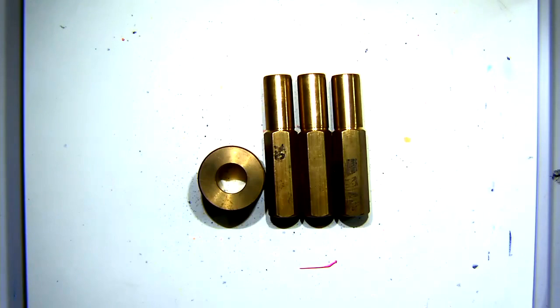And that hole is, as I played around with last time, I could put verniers and calipers on that hole and get a measure for that hole diameter, and even do it a few times, get a very accurate measure. But if we're in production and we're producing thousands or hundreds of thousands of them, we're going to get a range. And if that inside hole diameter is going to be within this zone, no less than, let's say, 10 millimetres, but it can be a little bit bigger. The hole can be 10.1 millimetre diameter. Well, that's what that cross-hatching is showing.